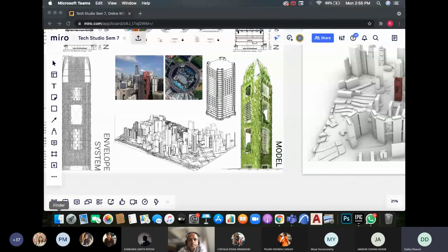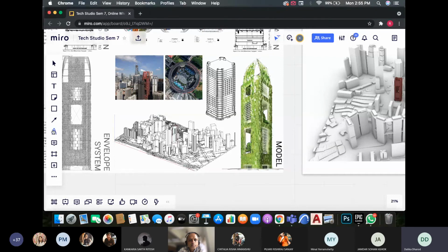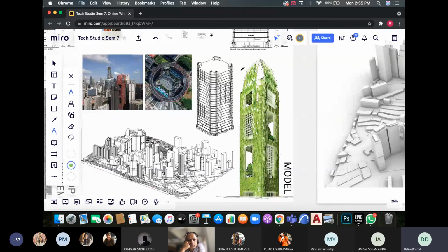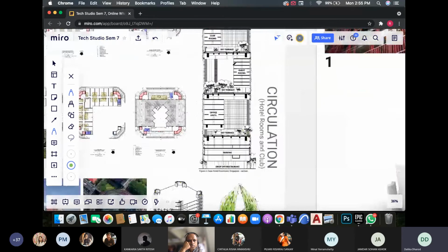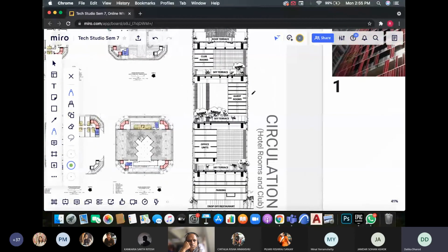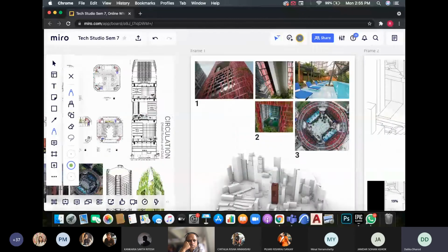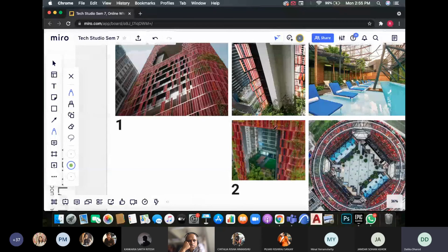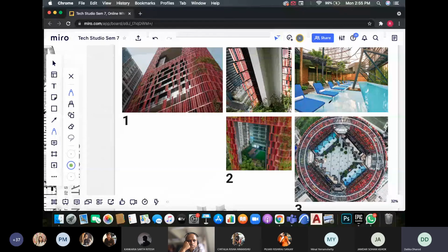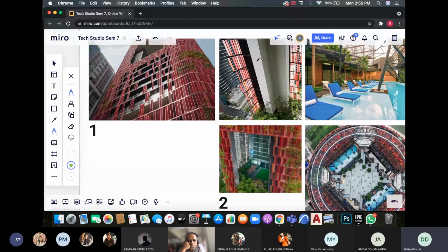So basically, our building is this Oasia building, which is in Singapore. It's basically a green building. The structural system is such that the inside core is made up of concrete. It has four major vertical cores, which also house the lifts at all four corners, and columns on the side which support the lift as well as the structure. In between we have large openings, which are sky terraces. On the outer side we have a skin, which is basically just an aluminium mesh, supported by freestanding columns at the base. At intervals it is attached to the inside concrete core through tension rods.